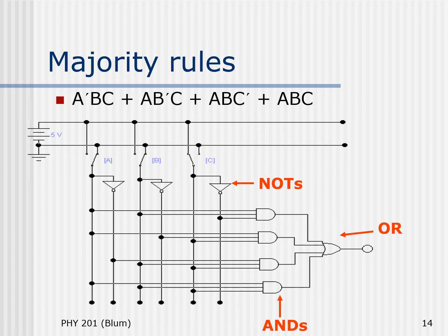So the AND gates give us our product terms, and we are getting all the combinations in our expression for majority rules. Then our final step is to OR those. The outputs of the 4 AND gates are all piped into a 4-input OR gate. The output of the OR is our overall output, on which we put a probe. When the circuit is functioning, the probe will light up if the output is true or high, and remain not lit up if it is false or low.